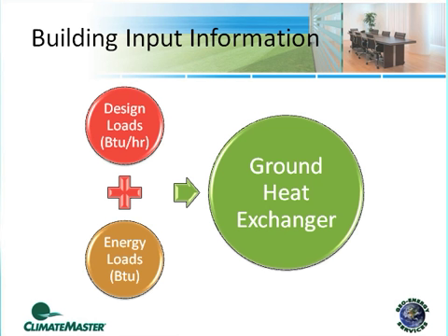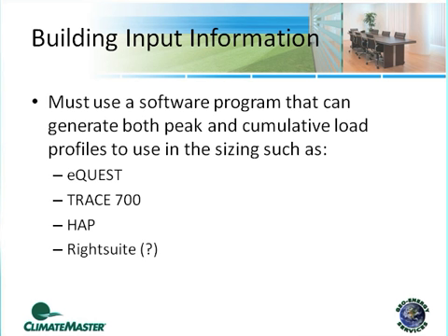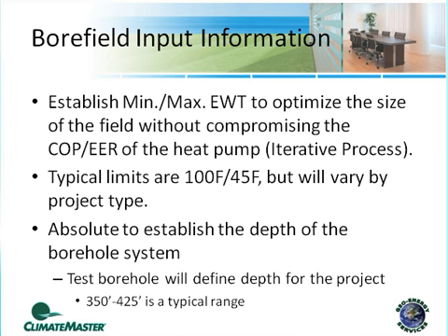All right? So here's a simpler pictorial way to look at it. Design loads, which is your BTU per hour, versus the energy loads, which is our BTUs, both have to carry through in order to right-size our ground heat exchanger. Now, here's some of the common programs that are out there that can do this: eQuest, Trace 700, HAP, and I believe Right Suite has that capability. There certainly may be a couple others. These are just to highlight a couple of those on the market that can do that. I cannot, typically speaking, take a residential program and design a commercial ground heat exchanger. That's an important thing to understand.